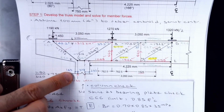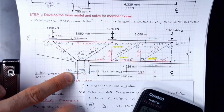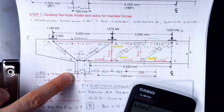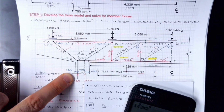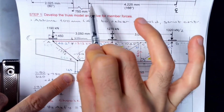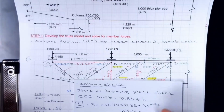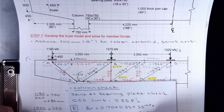And then the distance, what I allocated was 143 times 2, which is, sorry, not divided, times 2, 286 millimeter, times, you have to look at the column thickness. I see specified 750, 30 inches thick, 750 thick.